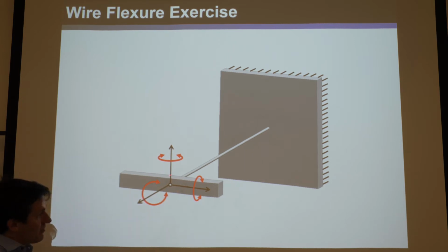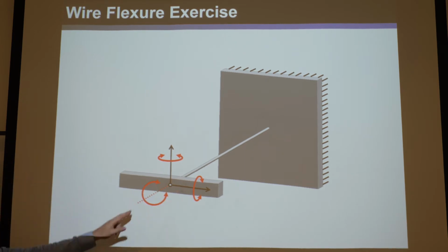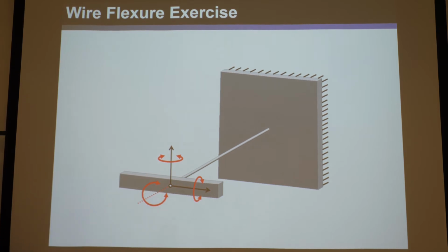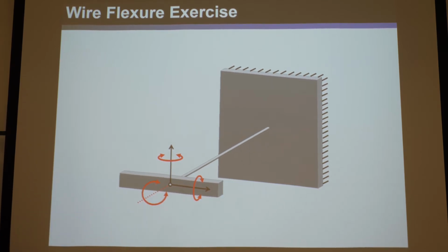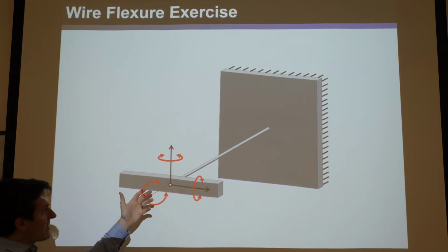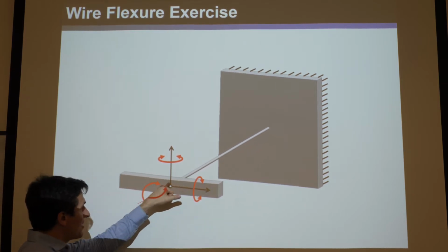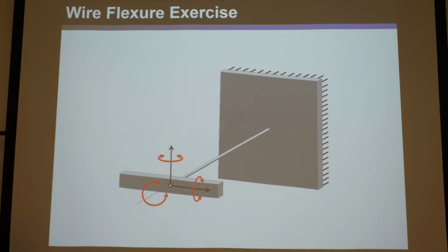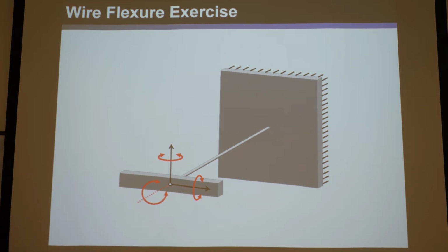With constraints, which we show here, this wire, you kill this translation. Now it has 5 degrees of freedom. Very good. And this is an exactly constrained system. So it's a parallel system, and it's exactly constrained because its wire is doing the single independent job of killing that thing, that translation. Okay?